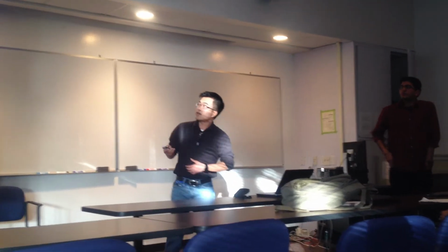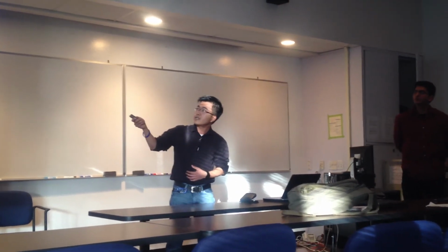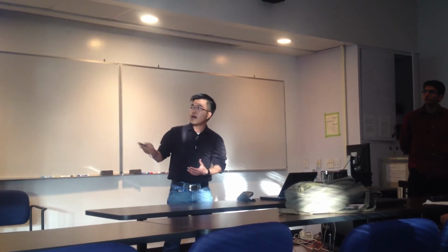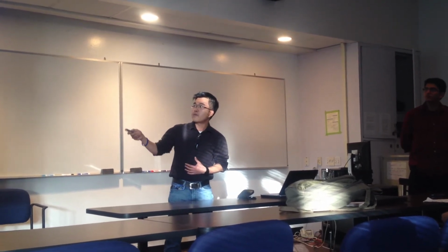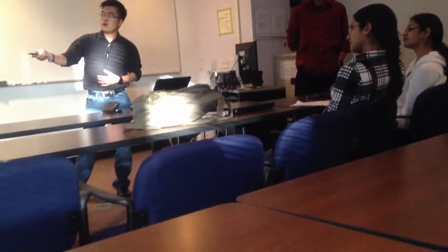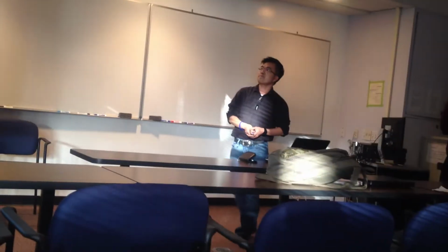First of all, the write interface, I have the write interface right here, and it works on the write clock domain. So I put the ports working on the write clock domain into one clocking block, and then a modport, and then I group the ports into the modport for the write testbed.